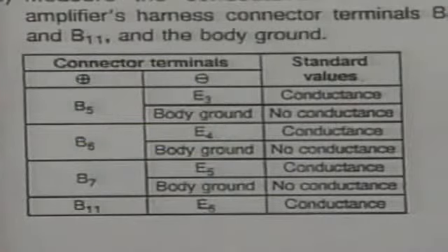Check the continuity of the wiring for open or grounded circuits at the corresponding pins. If the readings are not correct, the harness is at fault and should be repaired or replaced. If the readings are correct, the actuator is at fault. Troubleshooting flowcharts should also be used for failures which do not have a specific code. One such case is poor cooling with the compressor clutch engaged. If the preliminary checks did not reveal a fault, refer to the appropriate flowchart.